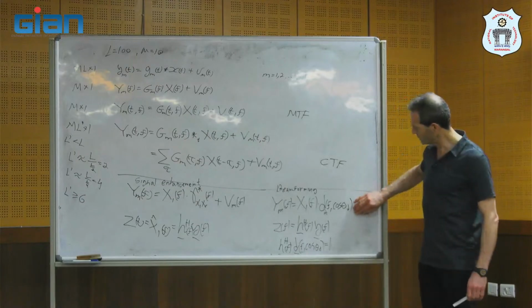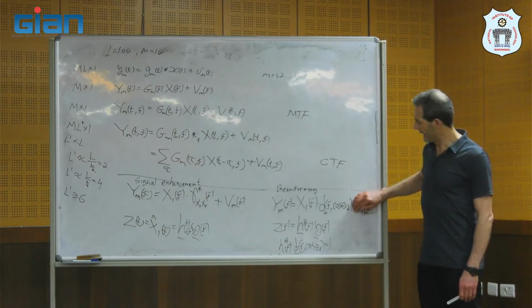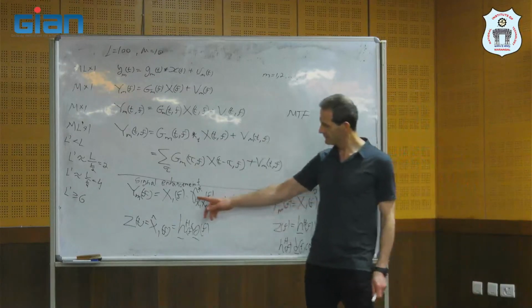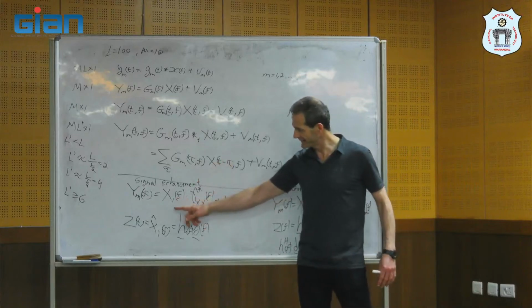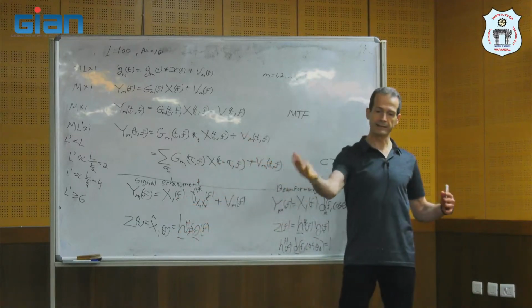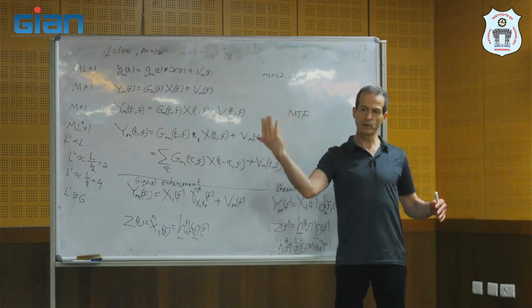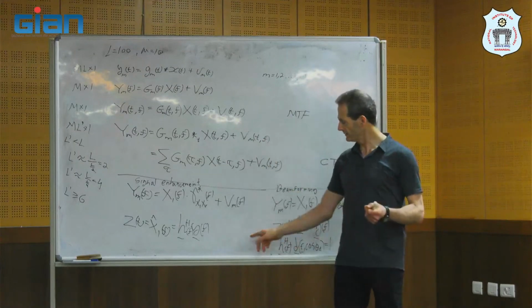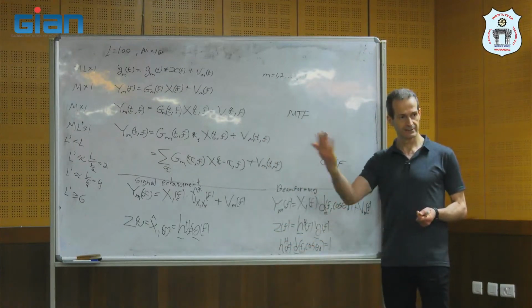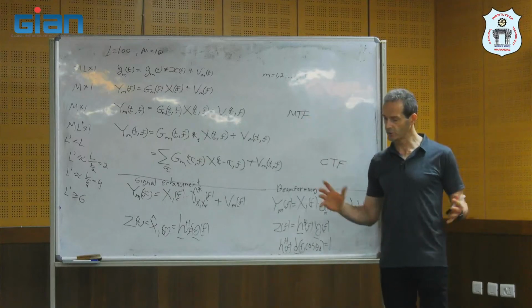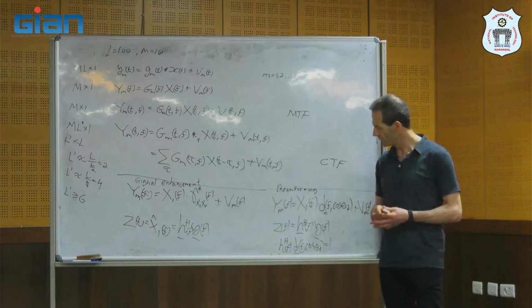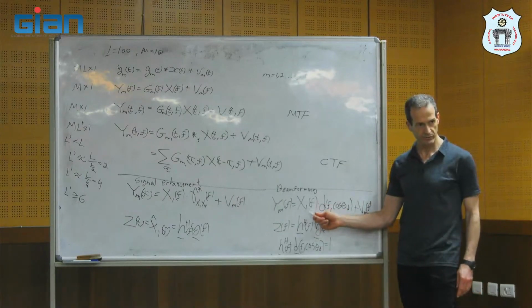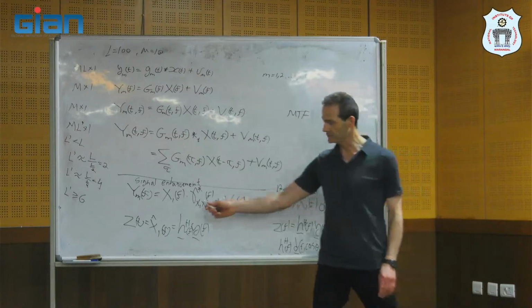But suppose that we don't have noise and we have some reflections from surfaces. Here, using this filter, we combine the direct path and the reflections into a stronger signal. Here, we suppress the reflections, we don't combine them with the direct path. So suppose that we don't have noise, we have less signal in a reverberant environment than we can have here.